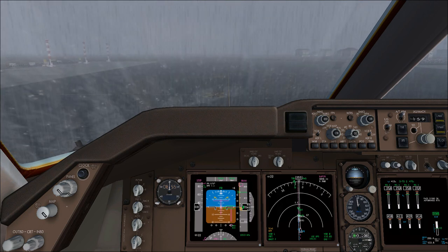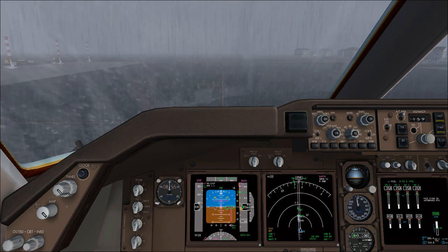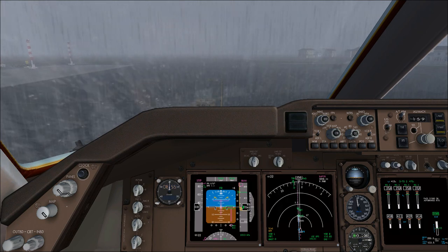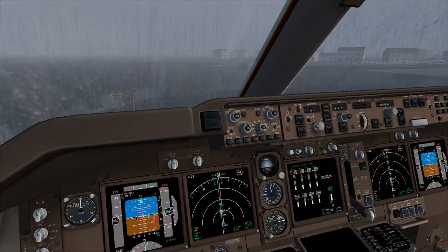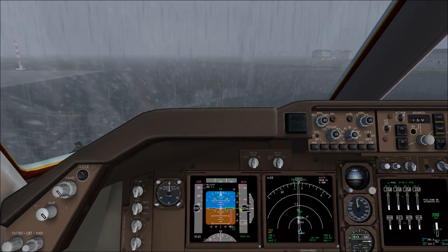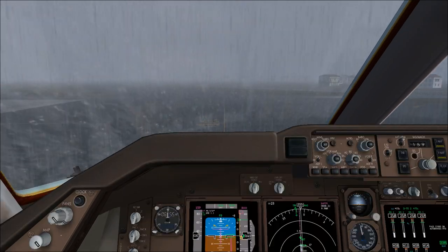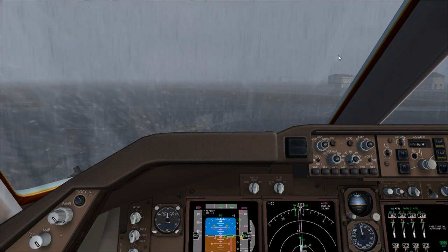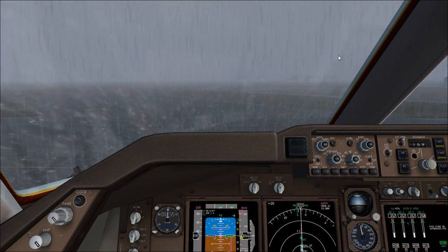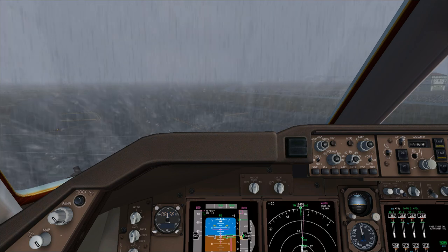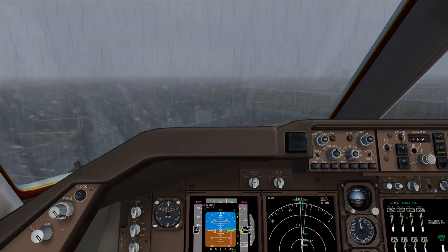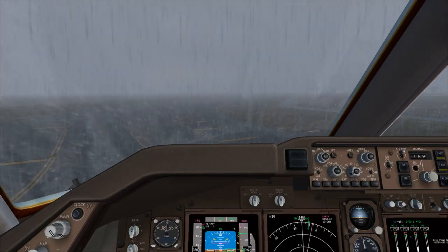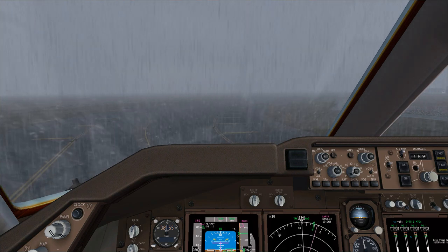And before takeoff, you have also to check that the engine oil temperature is above the standard temperature that was there at the start. We checked after warm-up. The warm-up time is usually 3 minutes, which is fine for the departure. So we had 3 minutes done, and so we are okay. We will take off after 3 minutes of the startup, so that's fine.